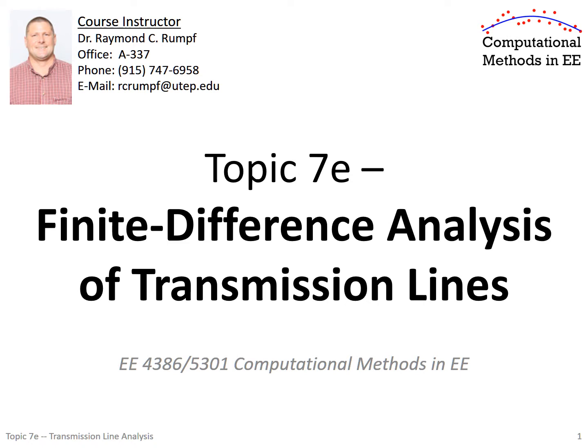We're also interested in something called the characteristic impedance of the line. So if we're watching a signal propagate down the transmission line, if we look at the ratio of the voltage to the current on that line, that gives us the characteristic impedance. And it's not so much that an impedance that is high is good or low is good or anything like that. Really what matters is when the line changes impedance, when there's a discontinuity and we start to get reflections. Usually we don't want that. Sometimes we do if we're making filters or things like that.